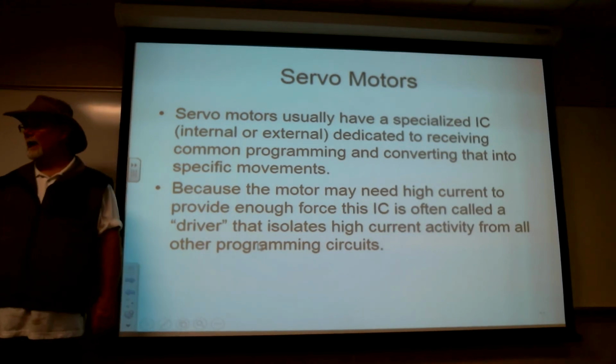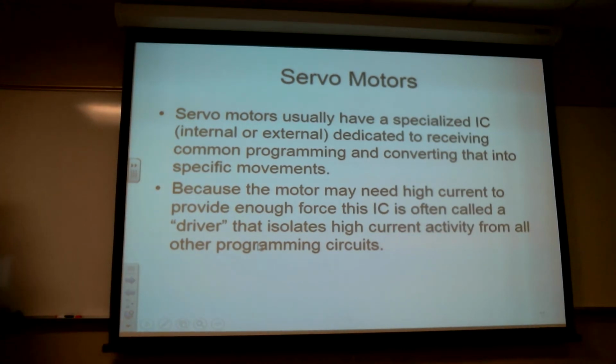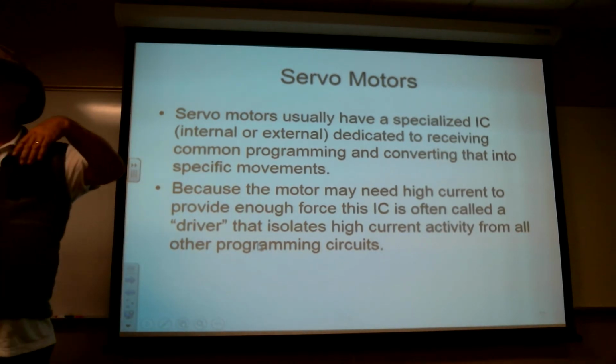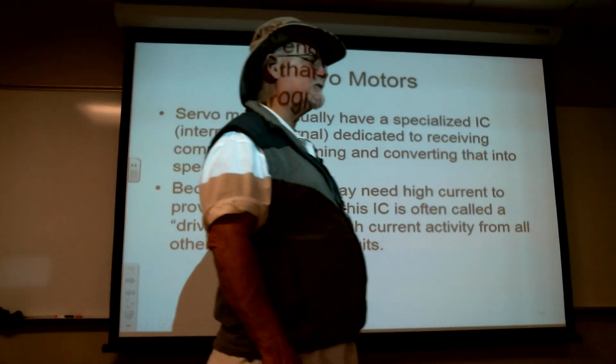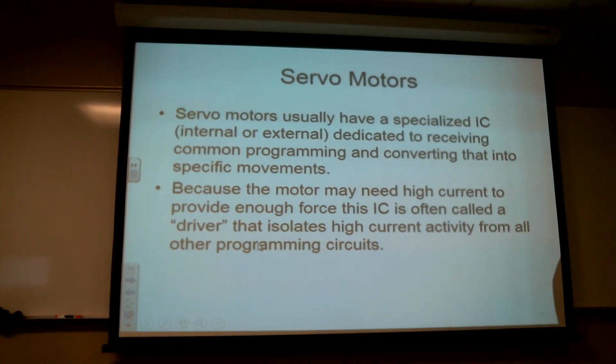And there are a variety of different code sets. What we typically use in the world of 3D printers, lasers, and CNC mills is a code that's been around since the early 70s, I think, called G code. There are actually about 213 or so different commands, but the bulk of the commands that are used are fewer than 10. Literally, it's a straight line from here to there, X to Y.